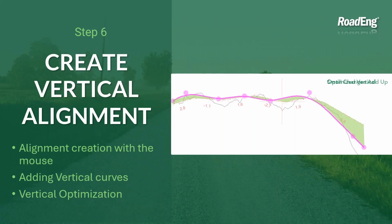And really just to highlight what that tool is doing is it's taking all those little cuts and fills and looking to minimize them, looking to minimize the excavation and embankment, as well as the transportation costs to move material as it solves the complicated problem of, where does the material come from to actually build this road? So all those small changes add up. And that's really what the major benefit of vertical optimization is, the cost reduction in earthworks through that process of adding up all the little changes and improvements in the alignment.